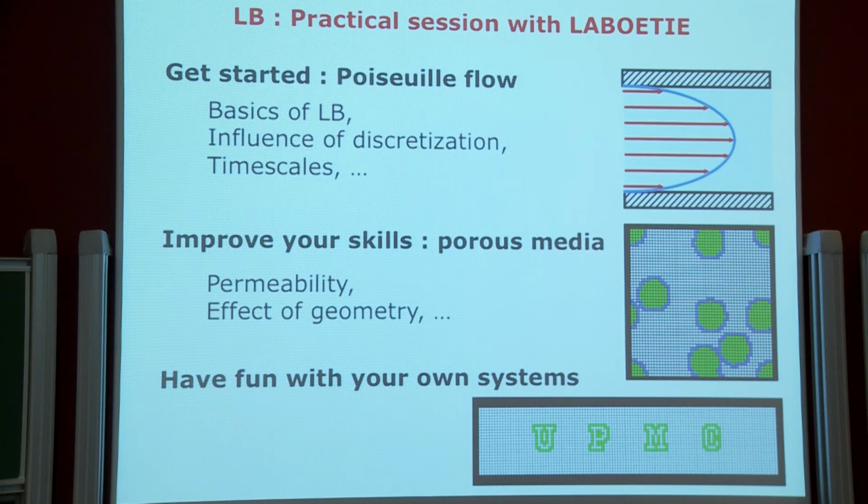You will have some analytical reference to compare with, and this will help you understand the influence of discretization, and think about the timescales corresponding to the transient regime, so how long does it take the fluid to establish the steady state, and so on. And that steady state is, of course, much more difficult to do analytically, but here it's very simple, simply propagating the Lattice-Boltzmann algorithm.